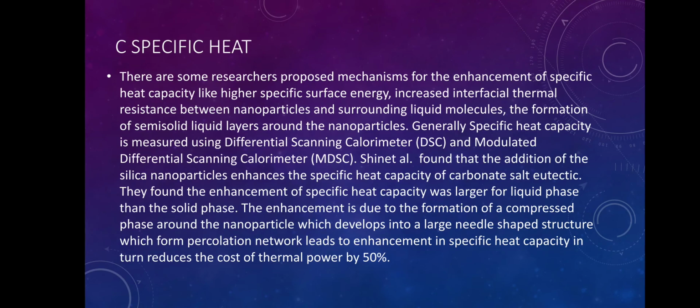Specific heat. Some researchers have proposed mechanisms for the enhancement of specific heat capacity, like higher specific surface energy, increased interfacial thermal resistance between nanoparticles and surrounding liquid molecules, and the formation of semi-solid liquid layers around the nanoparticles. Generally, specific heat capacity is measured using a differential scanning calorimeter and a modulated differential scanning calorimeter.